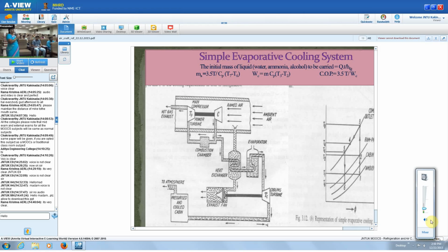So this type is used when the exhaust from the cooling turbine is at a higher temperature. So always we have to get T6 at very low temperature. So if at all T6 is at a higher temperature, then an evaporator is installed between a heat exchanger and a cooling turbine. And in the evaporator, some other liquid is used, not air here.